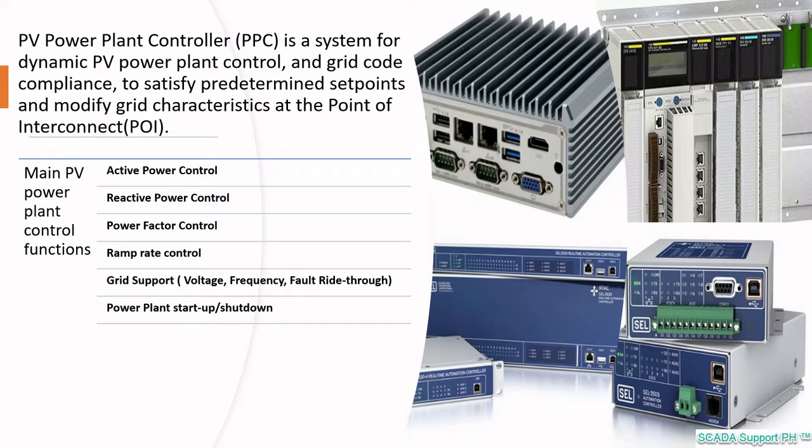In addition to regulatory components, PPC devices provide the additional benefit of remote controlling and troubleshooting activities that require the power plant to be taken offline. In order to assist field technicians, remote operation control operators can use the PPC to remotely stop or start those inverters, trackers, breakers, and other components.